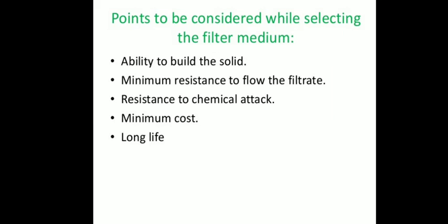There are few points that should be considered while selecting the filter medium. It should have the ability to build the solids. It should offer minimum resistance to the flow of the filtrate, meaning the filtrate should be slightly viscous so that it will move slowly through the filter and the solid matters will remain retained on the filter.